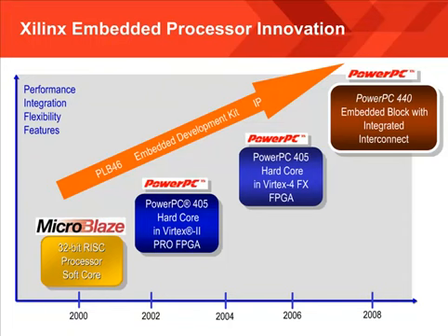Xilinx's embedded processor solutions include the MicroBlaze soft processor core as well as the PowerPC 440 hard processor core. Now, MicroBlaze is a soft processor core, which means that it is built with standard FPGA logic resources, including LUTs and registers, and it can target any of Xilinx's FPGAs. Now, MicroBlaze is a 32-bit RISC processor that can obtain performance over 300 megahertz, but this again will depend on the device family and speed grade, as well as the embedded system that you choose to build.